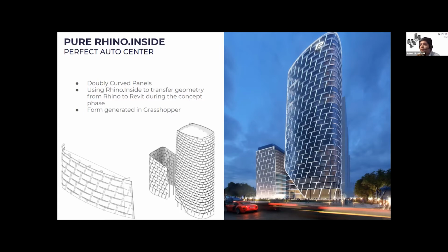They've not gone through a VE process yet, so the facade is insane. It's like 700 different panels, all doubly curved, not even radial to a point. They're all based off a different grid projection, which leads to all of them curving with completely different radii. This is much earlier on. They just completed their 25% or 50% DD. It was just to showcase that we're using Rhino.Inside even for transferring projects that are much earlier in the concept phase into Revit to document inside of Revit.